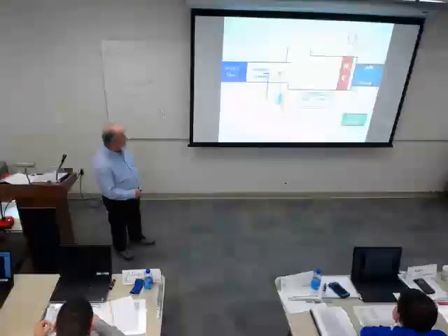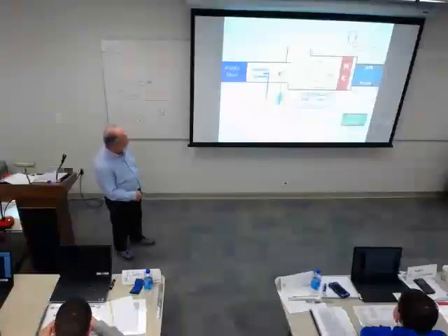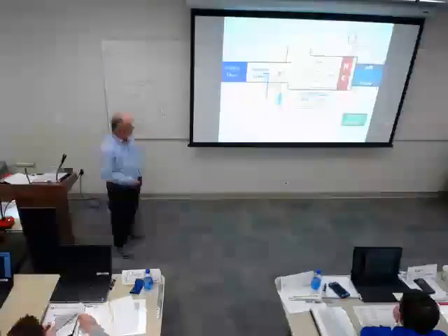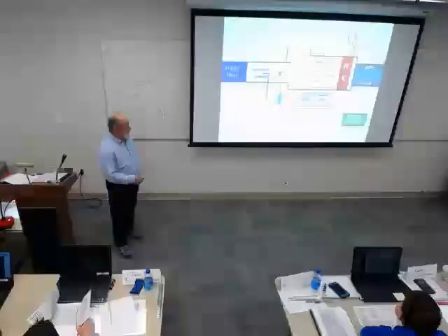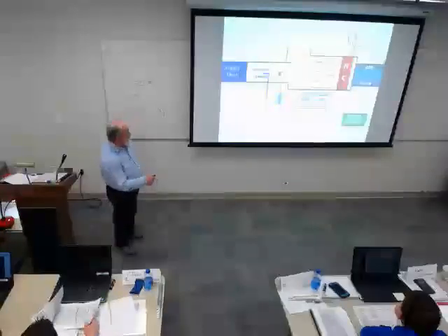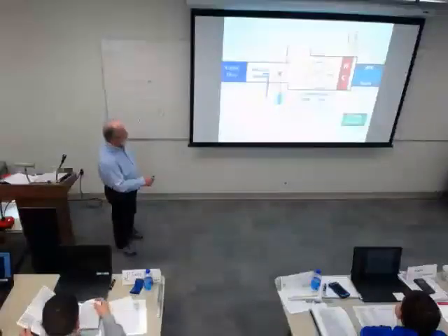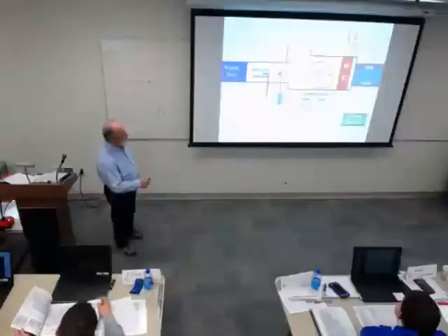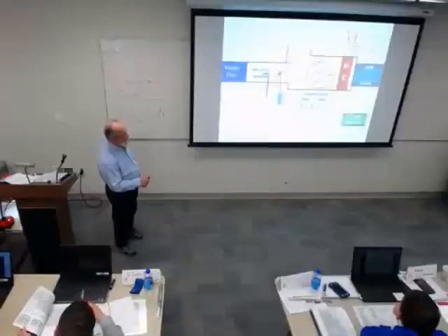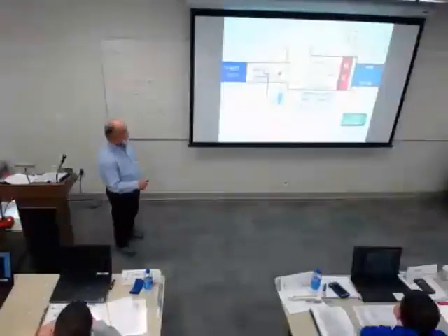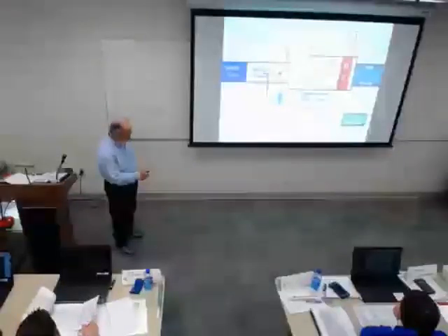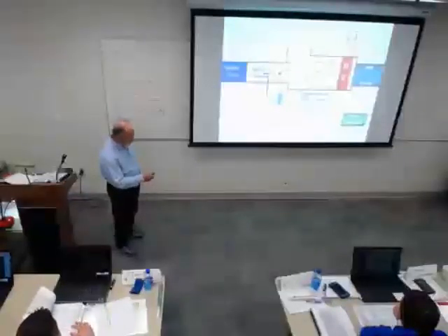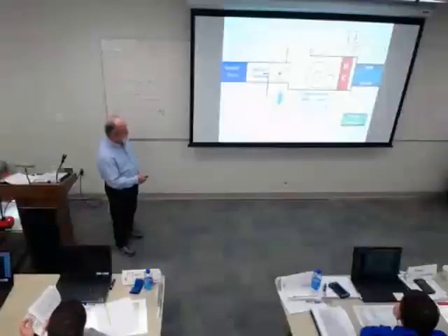Here's a VAV terminal, and this is a series type. That fan runs all the time. And when you balance it, you want to be sure that when at full airflow here, you have just the tiniest bit of air flowing into there, with a piece of TP. Tiny, tiny, tiny, or it affects the cooling. But the cool air comes through there, goes through the fan, and into your duct system.